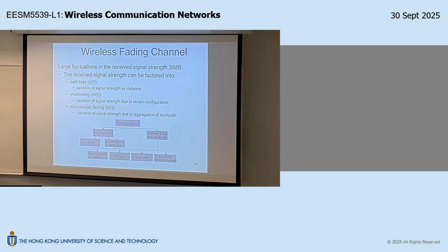For sure, path loss and shadowing would not be relevant, because you need to determine the physical layer algorithm, and that will be completed within a frame. For 5G, one frame is 1 millisecond. That is the time scale you have to work on. Within a 1 millisecond frame duration, the path loss and shadowing will be more like a constant, so they won't affect your physical layer design.